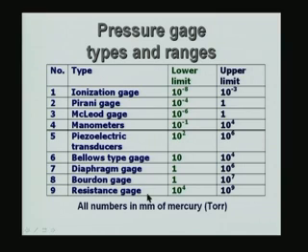The resistance gauge works as follows. If you have a material and it is subject to a pressure, it undergoes displacement or change in the shape, and because of this the electrical resistance of the material will change. Therefore, the change in the resistance is measured, just like we had, if you remember, in the case of temperature measurement, we had a resistance temperature detector where the temperature information was converted to change in resistance because of the expansion of the material, and this resistance change was inferred as being related to the temperature. Similarly, here the resistance will change, and it is in relation to the pressure which is acting on it.